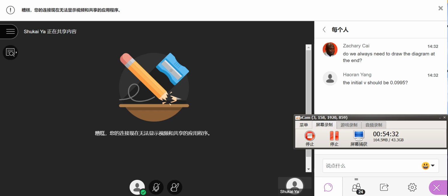Now we are required to calculate Tn from Td. We know that Td is equal to Tn divided by the square root of 1 minus zeta squared. So Tn should be equal to Td times the square root of 1 minus zeta squared.